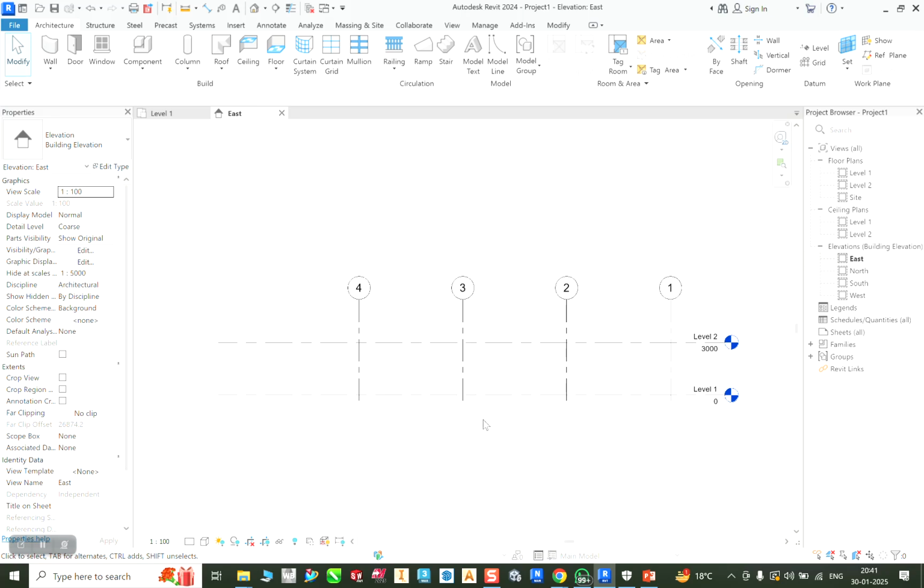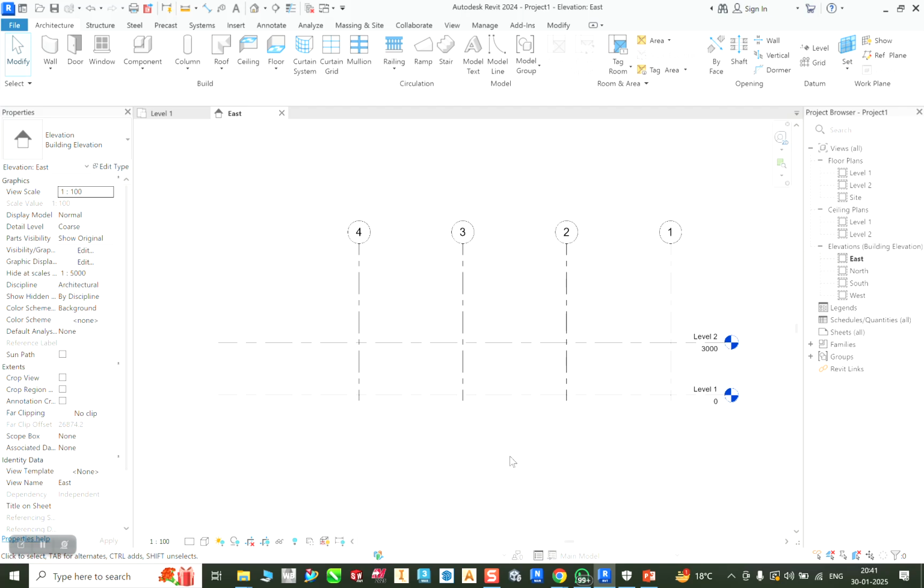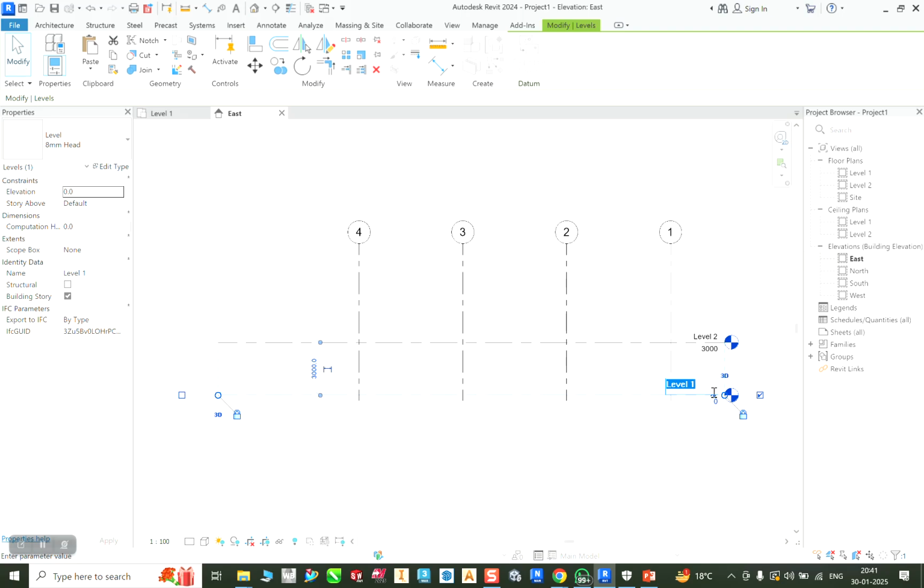So you can do that in the modification part. Even like this part, there is going to be a second one also, you can drag, pull and do that. So now I want to create one more level here. If I double click on it, you are able to write. So you can write ground floor, that is your ground floor. It's going to help you to work. Sorry, there is a spelling mistake. Floor. Okay, and just click here.